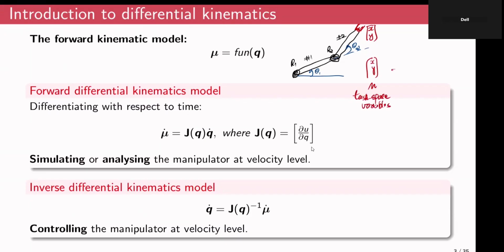And the variables that directly correspond to the input into the motors, for example, if you consider this robot to be of 2 degrees of freedom, you will be attaching a motor directly to the joints, and the input to these motors, which correspond directly to the joint variables theta1 and theta2, we call this vector the joint space variables.